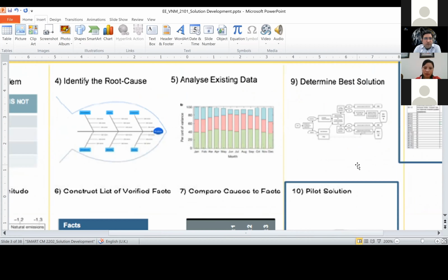So let's say we have one problem which had 2 or 3 root causes. Taking again the example of steam leakages, one cause was that the equipment is rotten or old. Second cause is that the maintenance data does not show that the maintenance team actually did any analysis on leakages or pipes. And third is that the procurement policy does not show that we are preferring energy efficient solutions.